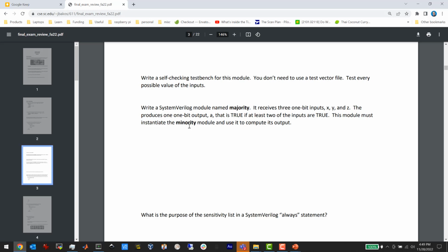That way the CPU will be putting out the value from every instruction. And then you could do a self-checking test bench that would check the output of the GPIO out. That's one option. But sometimes it can be hard to write a self-checking test bench. In this case, this is a simple circuit, so it's essentially a truth table. So you're just checking all the rows, the outputs of the truth table.